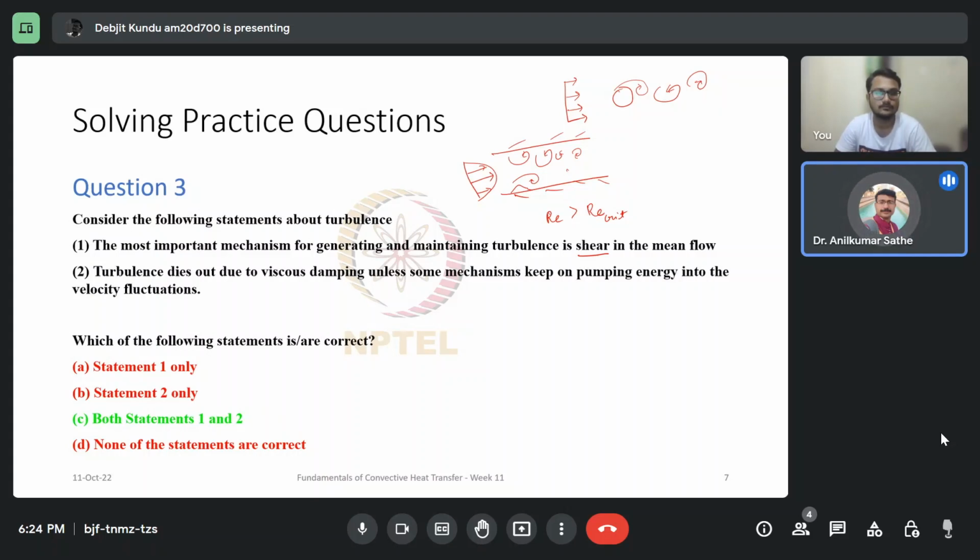Then various parameters: the pitch, the shape of the wings, which I call winglets, and the angle with respect to the flow axis of the pipe were changed, and that parametric study I did in MTech, and I developed my own correlations for it. The basic idea was to induce some turbulence with those fins, and as a result the heat transfer would enhance, right?